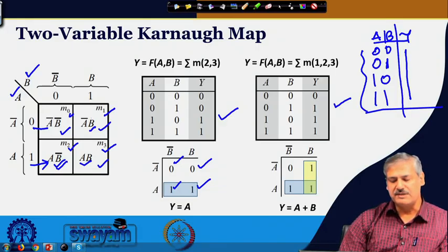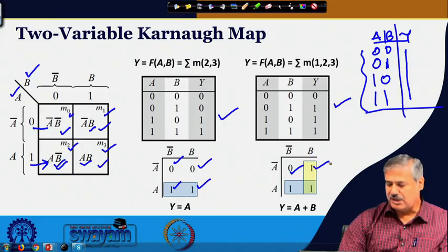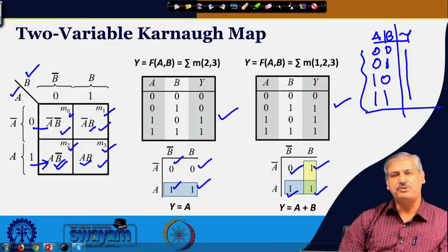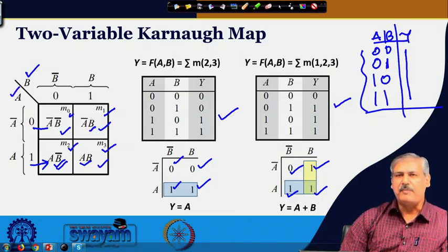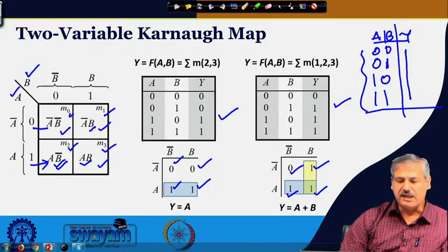So, this is what we can see as a mapping. And the one that we had seen before: for 0 0 it is 0, and for the rest of the 3, 0 1 it is 1, 1 0 it is 1 and 1 1 it is 1. This we have already seen. So, when this truth table gets mapped to a Karnaugh map, it would look something like this.